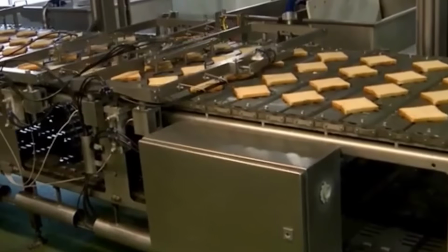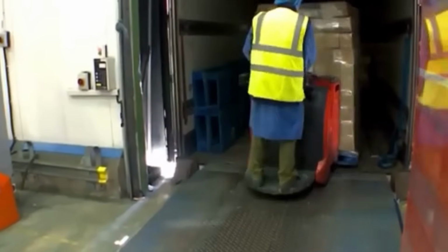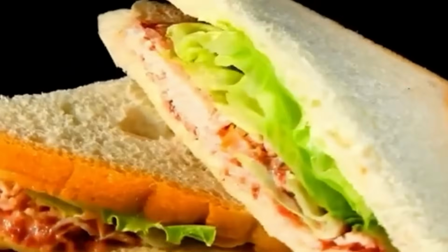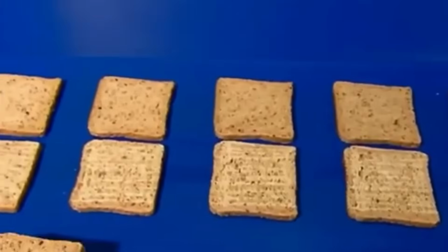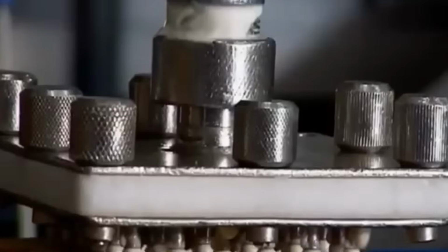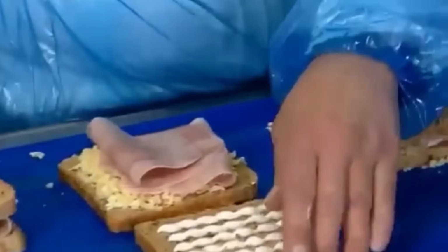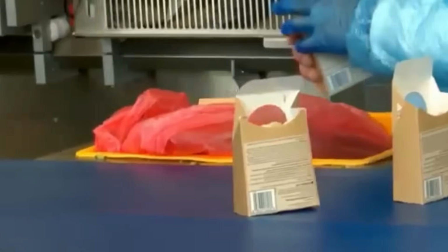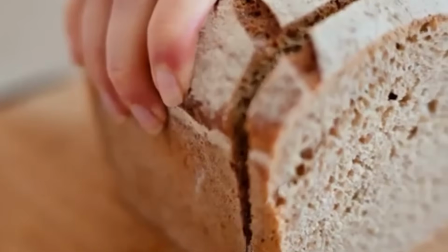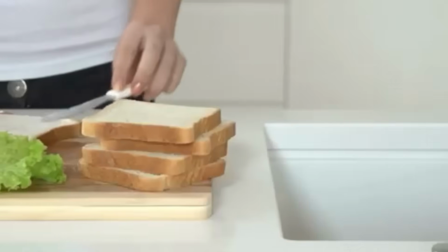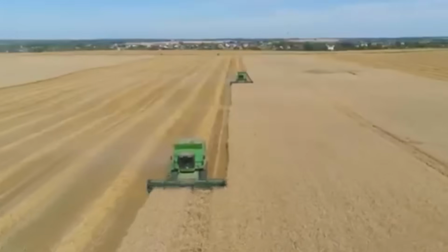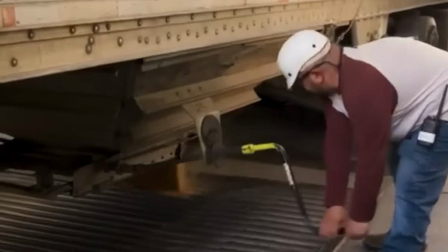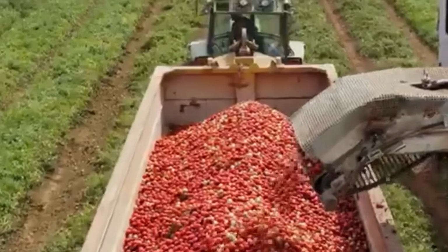Once sliced, the bread slices travel by conveyor to a pre-alignment station, where camera-guided sensors and rotating guide arms ensure every slice is positioned in the exact orientation required for the next phase, which is the laying down of the base slices. These are distributed in pairs or rows, depending on whether the line is configured for single or multiple sandwich formats, and set evenly onto the moving belt with equal spacing between each set.